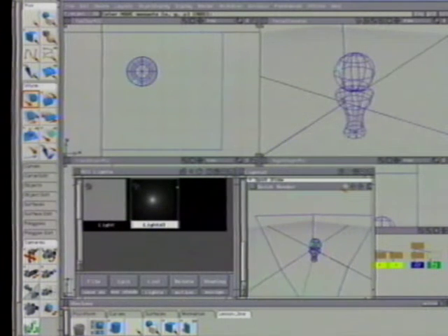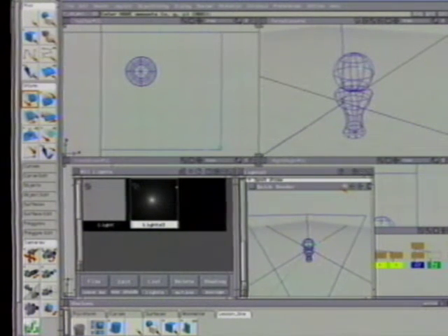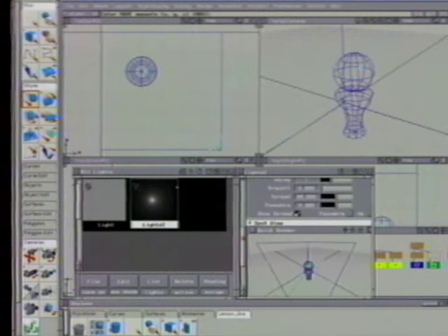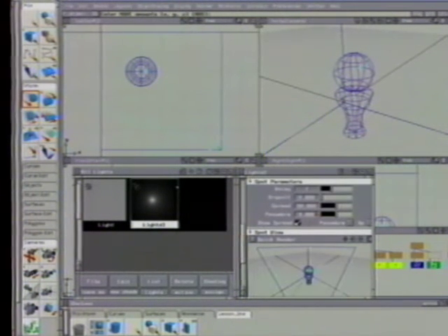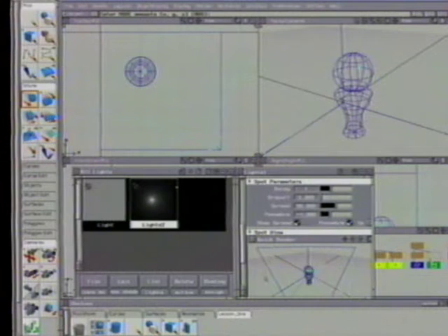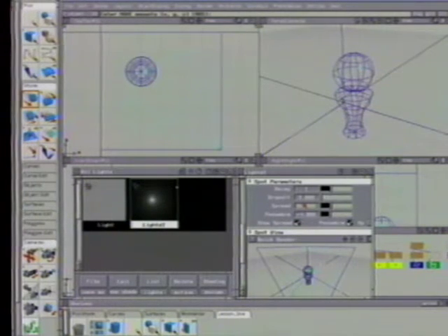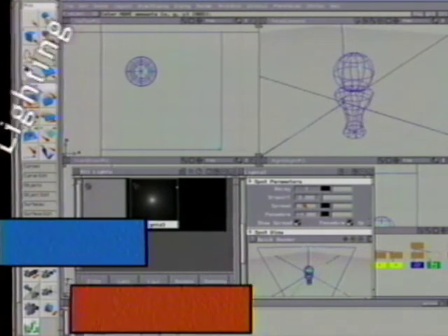Adjust the view icons in the view and you will see the parts of the light move in the modeling views. Scroll up to the Spot Parameters section. Click to turn on the penumbra, then change the penumbra value to -4. The edge of the penumbra is shown in the spot view. The penumbra is the area where the light will soften as it hits the scene. Now change the spread to 60 degrees. Only part of the scene will be lit by the spot when you later render.